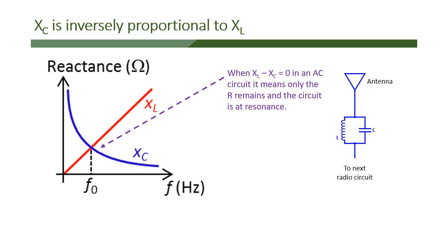So if you think about this, if we have all these resistances, X of L plus X of C plus R equals the entire impedance of the system, and we get to a situation where X of L minus X of C cancels each other out, the only thing that remains is R, which means that is the maximum current flow in this circuit. Because if it was anything other than the same frequency that cancels these out, there would be additional resistance from L and C. So if X of L is not equal to X of C in magnitude, then there will be values that we're going to add together to R, and it'll be higher than when they're canceled out. So when L and C cancel each other out in a circuit, it's at resonance. And resonance only occurs at one frequency. And so this antenna can be designed to operate so it maximizes the current from the antenna to the radio for one specific frequency.